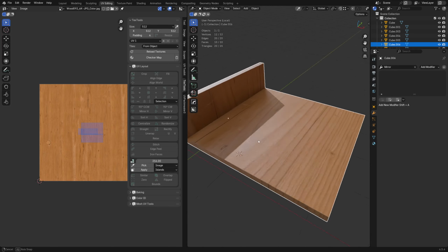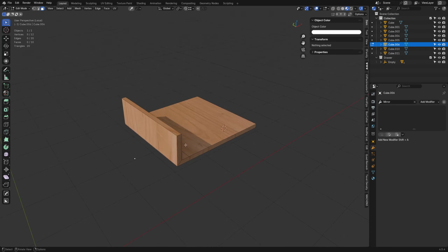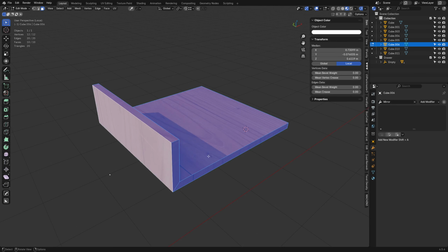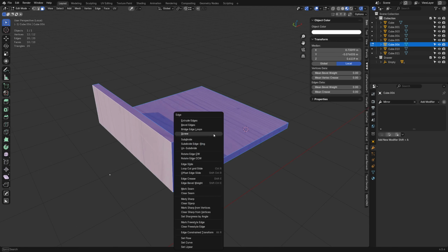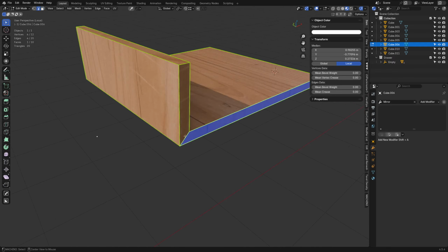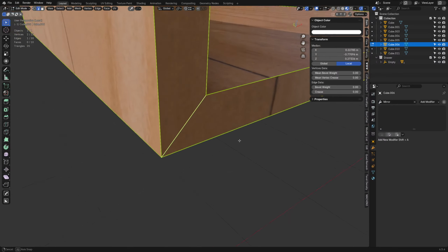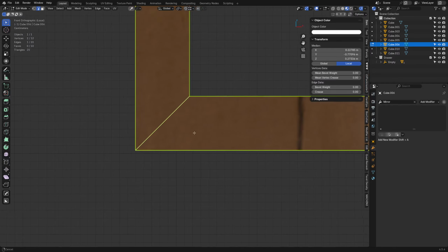So what we can do a little bit different though is we can make islands with our UVs, which is quite useful. So let's grab this whole thing here, Control E, and we can do mark seams. And it's going to mark every edge as a seam first, right? This one you don't necessarily have to do this corner like this, but a lot of times this type of furniture, it does do something like this, right? Where they have these 45-degree cuts out to the corner. In this case, this actual object cuts down like this.